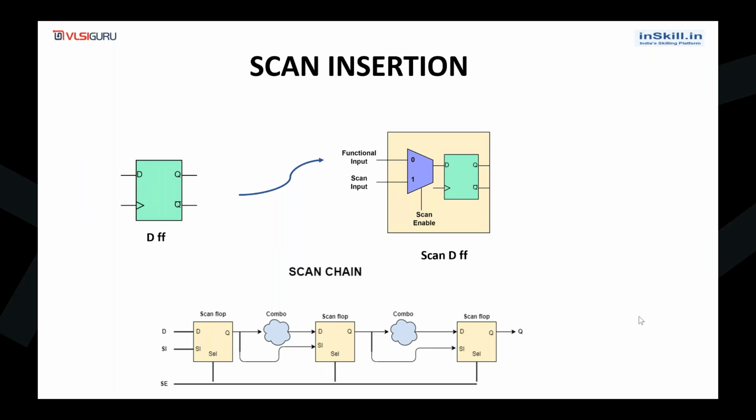Now what is a scan flop? How are the scan flops stitched into a scan chain? What is a scan chain? How does a scan chain function? All those things we will try to discuss in the next session when we do the course. As of now, just remember that scan insertion means all the normal flops will be converted into scan flops, and these scan flops will be stitched into scan chains.